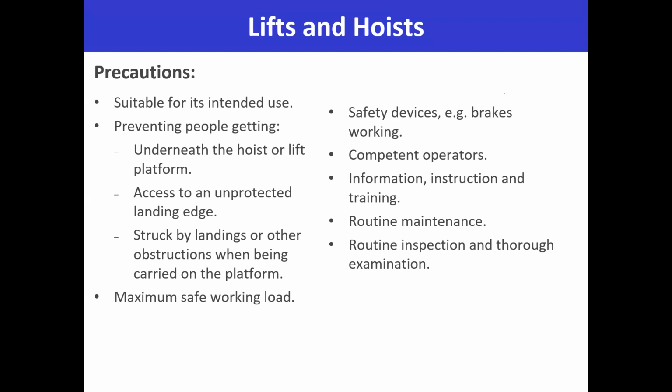Access to unprotected landing edge should be controlled. Watch out for being struck by landings or other obstructions when being carried on the work platform. So when you're being raised or carried to the work platform, you can get hit by structures here and there. Maximum safe working load should be followed and you should never exceed it.